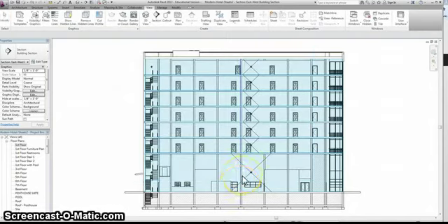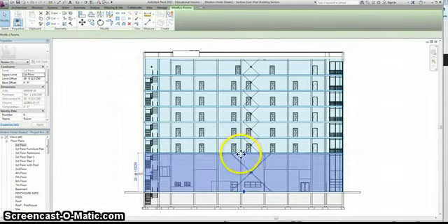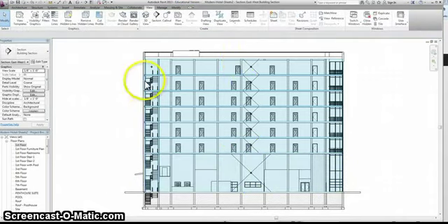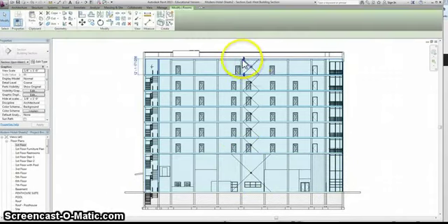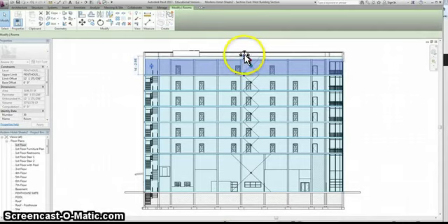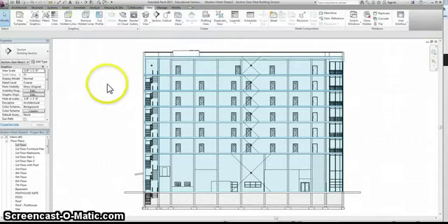Click Apply and OK. So this will bring up these blue X's, and you want to make sure that each boundary extends all the way to the ceiling and floor of the next floor. Otherwise, it'll have problems exporting the GBXML file. So that top floor will extend. Okay. And now we're ready to export the file.